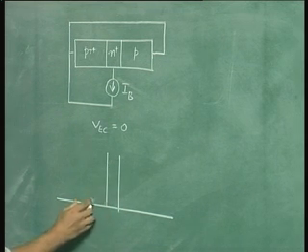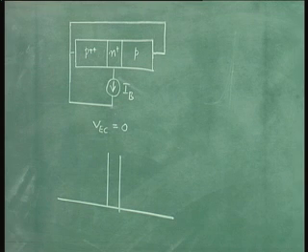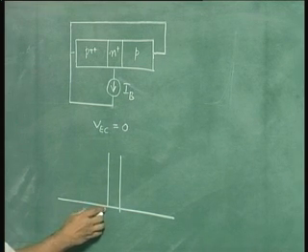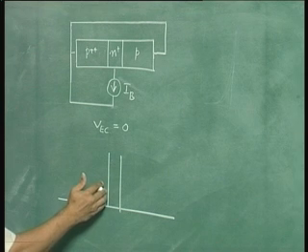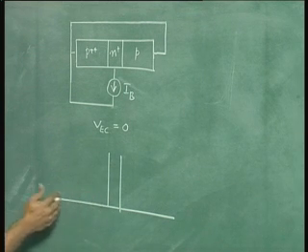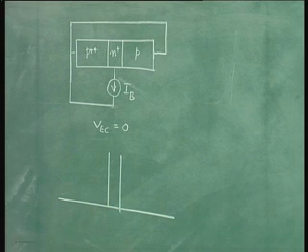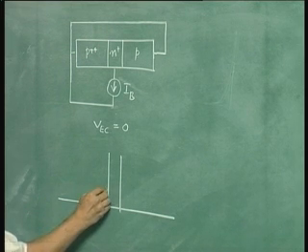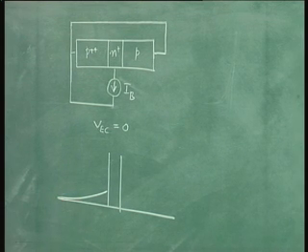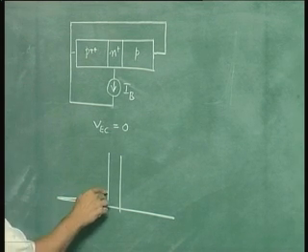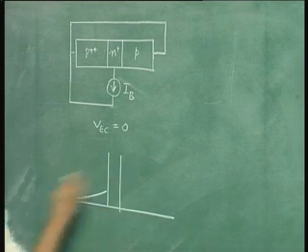and the diffusion length in the emitter, as we have noted, is 33 microns. So strictly speaking, the distribution of the excess minority carriers would extend over a fairly long distance here as compared to the base width. So let us draw it something like this. This is the excess minority carrier concentration in the emitter. We are going to assume long emitters, okay.